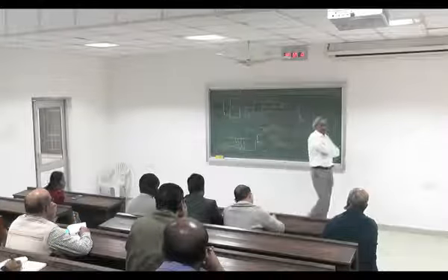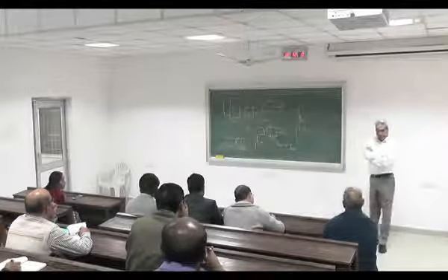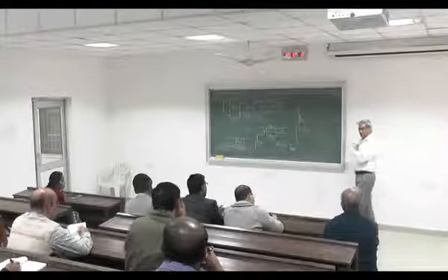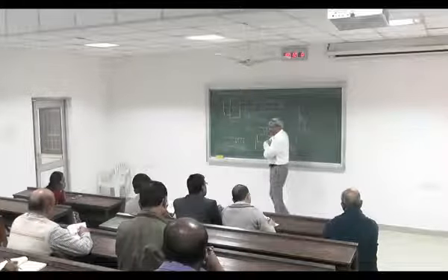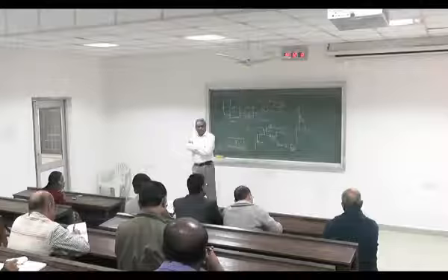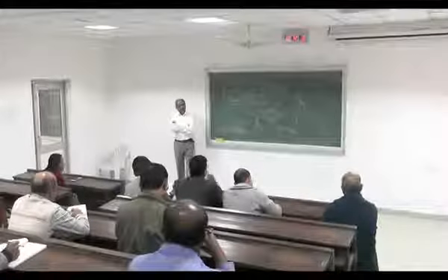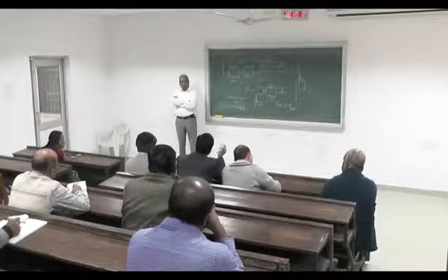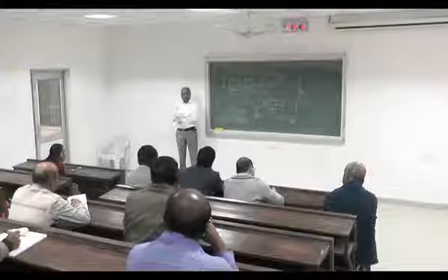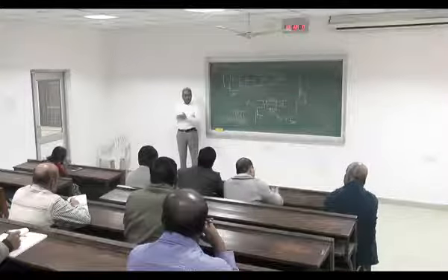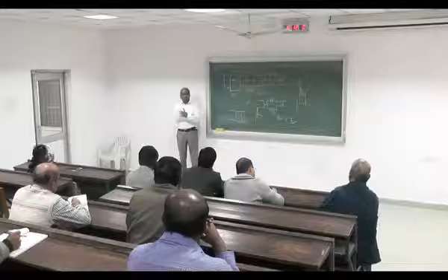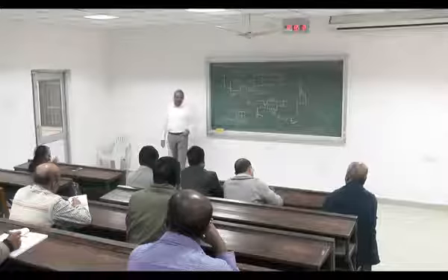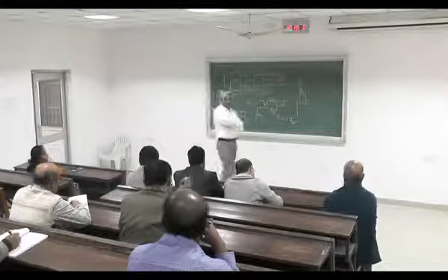So if you really want to go to very high switching frequencies, then the resonant circuit enables you to go to those frequencies because you are able to absorb the parasitic components of the transformers, rectifiers, layouts, all those things. So these components will be more prominent if we operate at a high frequency. And since they are more prominent at those higher frequencies, they will create more problems. But these components are absorbed in the resonant circuit, so the problem is not there.